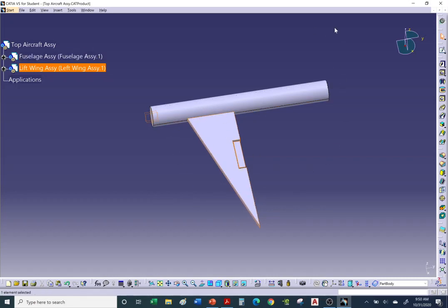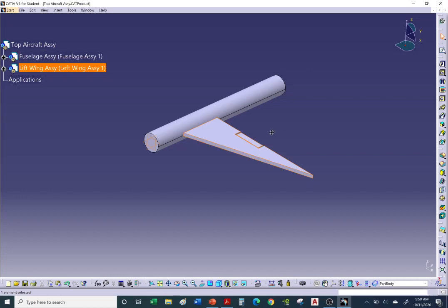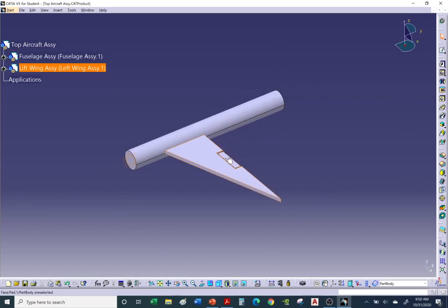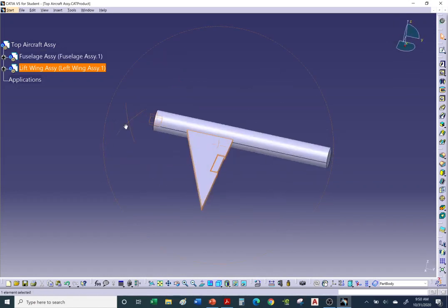Same thing with the rudder. I would now insert a rudder assembly and then model the rudder in part design. Okay, so this is top down. You're modeling the parts where they go in the aircraft, and this is referred to as context modeling. You're modeling the parts where they go in the aircraft with respect to the aircraft coordinate system.